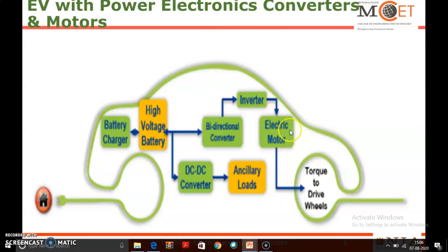And this is an electric motor, AC type motor. So we know that a battery can supply only DC power. Hence, the inverter system is required to convert the available DC from the battery into AC, and this conditioned and controlled electrical AC signal is fed to the electric motor for its speed and torque control mechanism of the mechanical transmission system of electric vehicles.